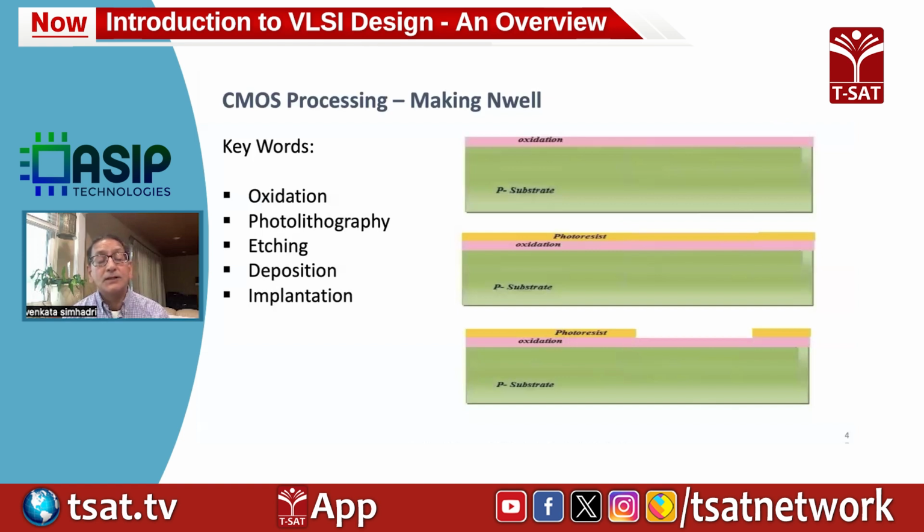Then the photolithography. It's a process to create different patterns on the wafer to identify where to make your deposits of metals, for example, or make your implants, for example N plus implant or P plus implant. Then etching is a process.